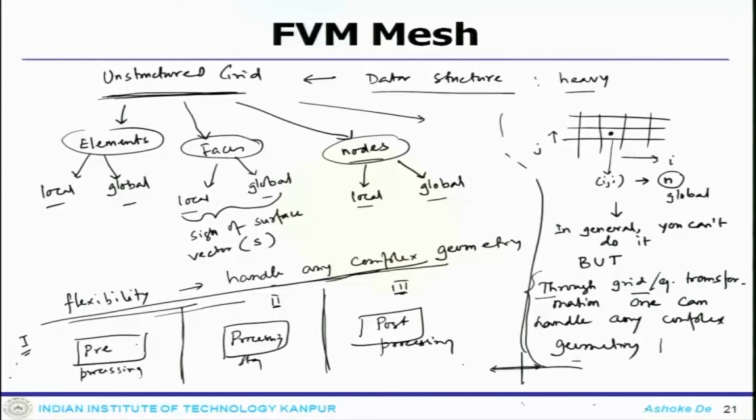That means it involves grid generation. So, whether it is structured or unstructured, irrespective of that, it involves grid generation, and for a problem of some realistic nature or complex geometry, it actually takes a lot of time to generate the grid. So, this takes care of your mesh generation, number 1. Number 2, one also has to properly assign the physical boundary condition to the computational boundary condition, because your code will only read that information.